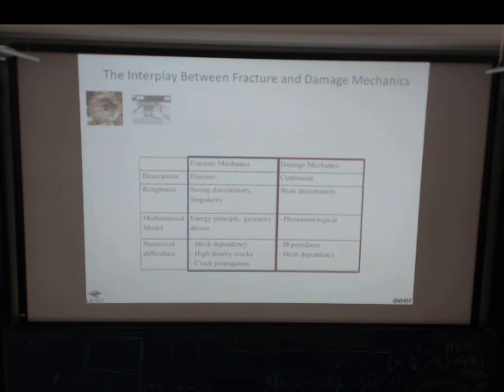Again, you can argue how you get the form, how you obtain the material constants and things like that. And then when material fails, as described by damage mechanics, there's a so-called softening response that happens. If you look at, say, the simple Hooke's law, you pull a material in tension, and as you apply the force, the displacement gets bigger. But once the material fails, then it will drop. So the stress-strain curve or the force-displacement curve will have a hardening curve and then softening.